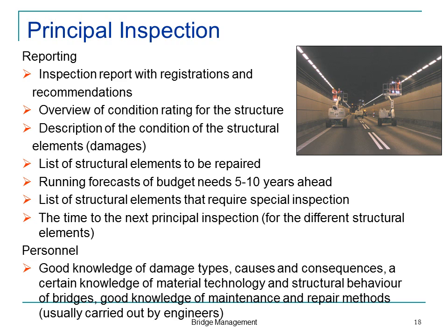What equipment do we use for these principal inspections? I would say very little. Pen and paper, camera, a hammer to bang on things to listen to how they sound.